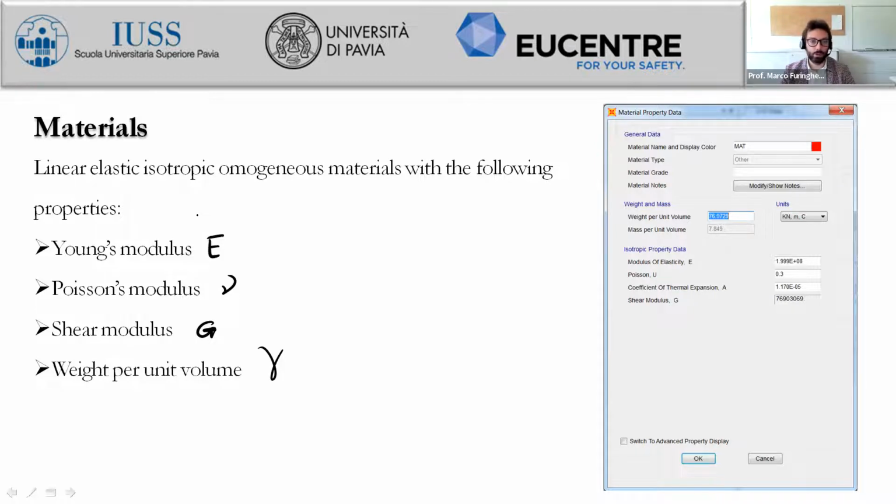What I was able to do was just a pushover analysis, which took something like half a day for, I think, 10 steps to achieve the maximum displacement allowance of the frame. So there are also issues for nonlinear materials, but they are time consuming.